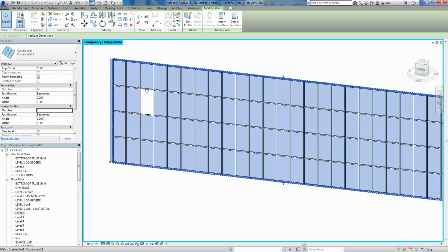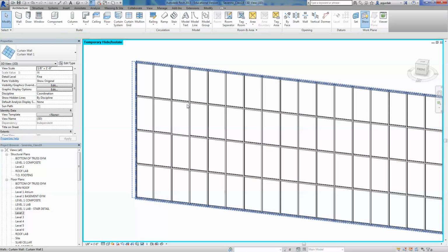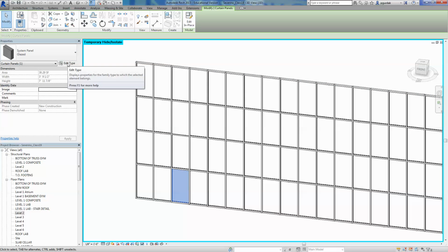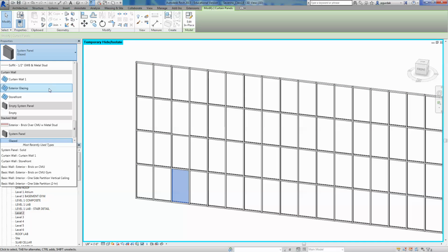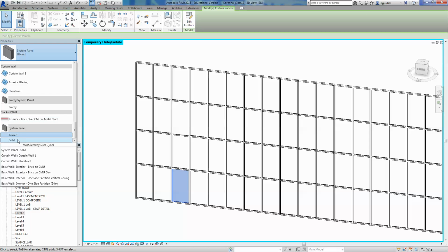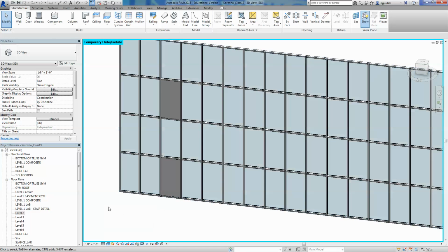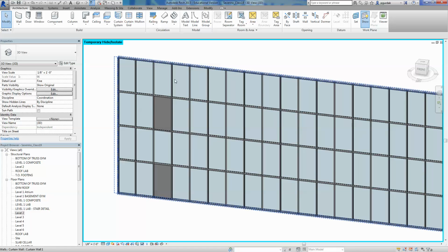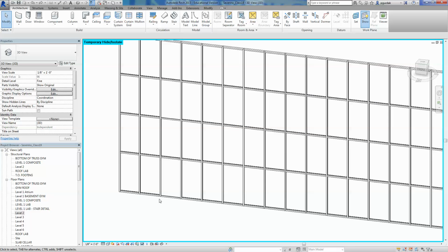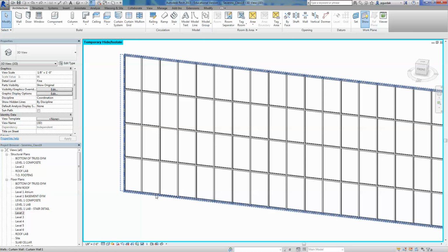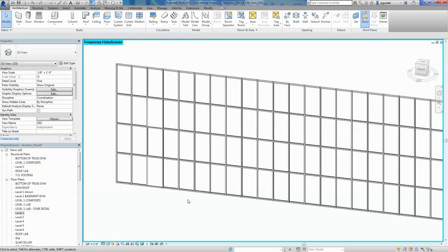There you go. Now, also before I started recording, I changed one of the panels, and you can go next to a panel and tap to select the panel and change it from a glass system panel to a solid one. Now you don't see it very well here until you go to the shaded mode, and you see how I changed these two. This one before recording, this one right now. Okay. So what if you want to make one of these panels a door, which is the idea that I'm asking from you right now.